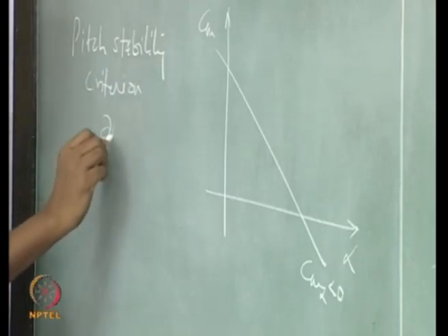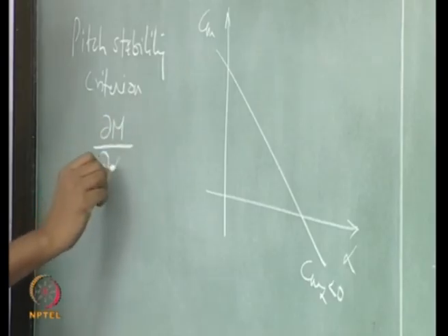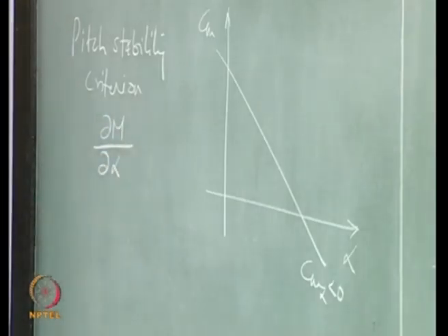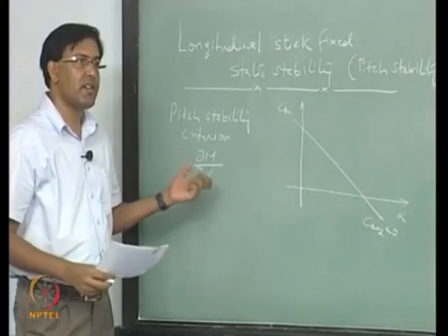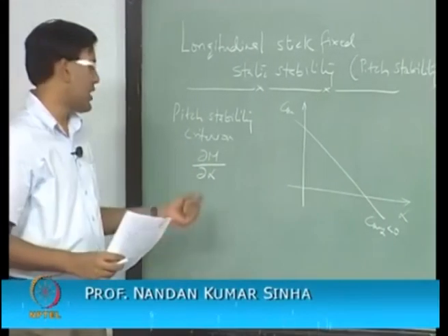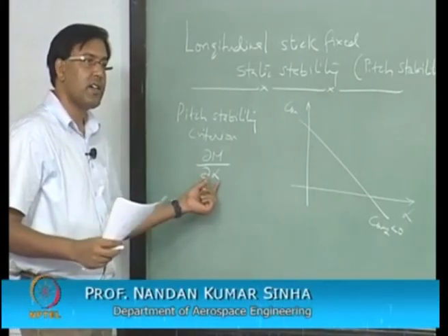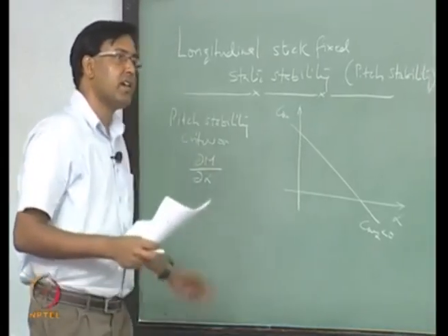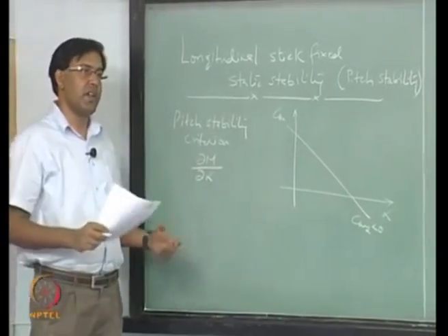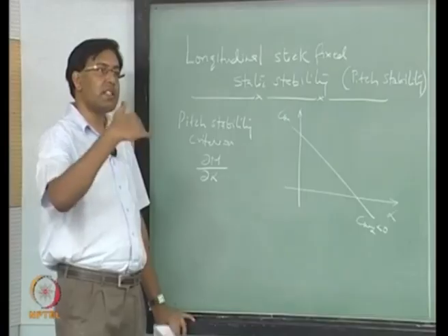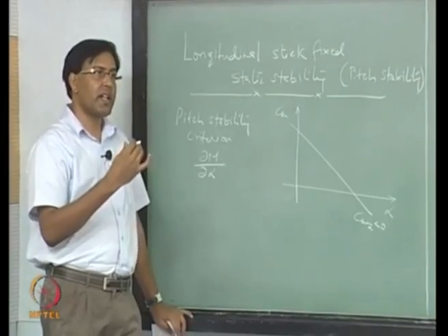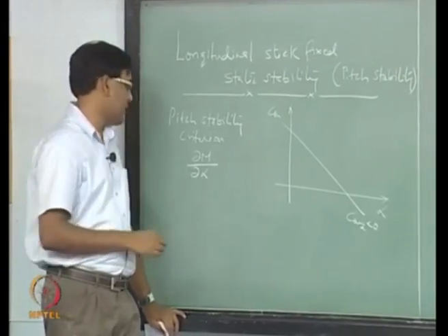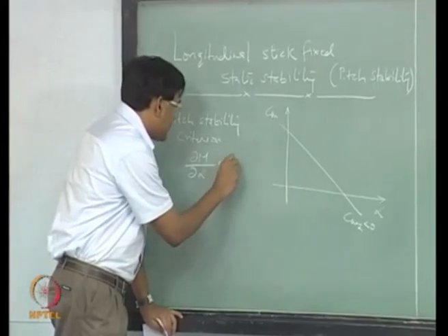A change in pitching moment because of a change in angle of attack: a positive change in angle of attack should automatically result in a negative change in pitching moment, so that the tendency of the aircraft is to kill that extra angle of attack.